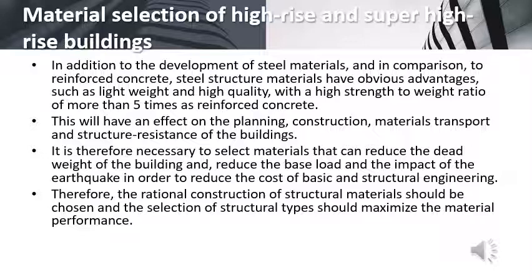Therefore, it's necessary to select materials that can reduce the dead weight of the building, and meanwhile, the weight reduction could decrease the base load and the effect of earthquakes, so as to reduce the cost of foundation and structural engineering. Therefore, rational building structural materials should be chosen, and the selection of structural types should maximize the material performance.